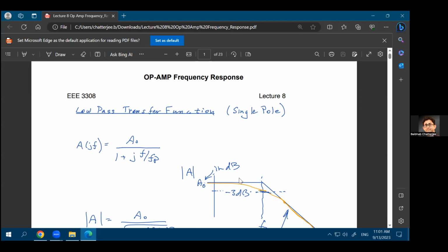Question? So the graph on the bottom there, that's the graph of the gain, right? That's the graph of the gain. So transfer function, voltage gain, everything is the same. You might be asked what transfer function means. It's the output voltage divided by the input voltage. That is the voltage gain. Sometimes you'll see it mentioned as transfer function in some books. Some books will call it voltage gain, some books might call it just gain, but it all means the same thing.